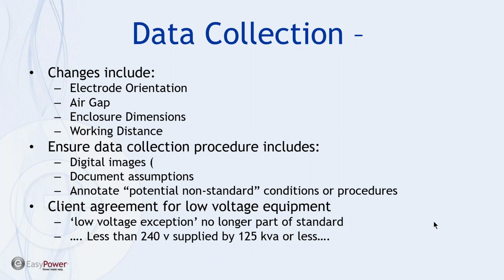And that is make sure you have a very methodical process when you're doing data collection. What I mean by that is take a copious amount of digital images, and when it comes to an enclosure dimension that you may or may not suspect of being non-standard, it makes sense to have some sort of a yardstick or a non-conductive reference point in the image that you take of that piece of equipment.